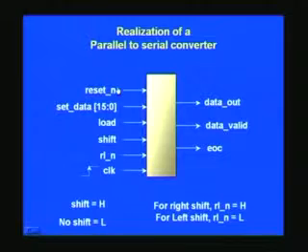So let us say we want to once again reset the system with a power on reset or system reset, and you want to load a particular value at any point of time. You can assert this load, and prior to that you can set the data using this bus, say 15 through 0, that's 16 bits, as we stated earlier as far as the width is concerned. And so the output will manifest here.